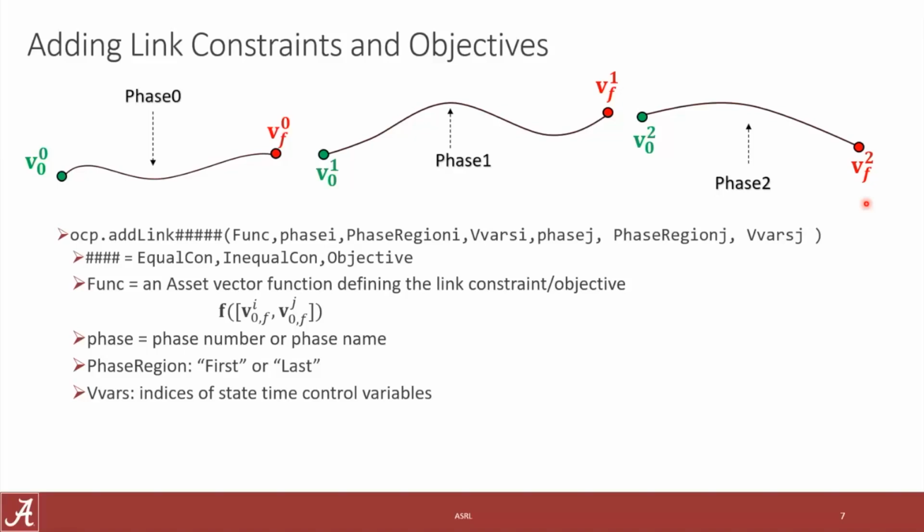We've even had an example where we had a known deployment condition, a known primary spacecraft that we were going to be deployed from on a mission. So we could just integrate the path of the primary payload, and then set a constraint that our initial condition must start somewhere on this integrated path, and then optimize the best time to deploy from our primary to go out and do our secondary payload mission.